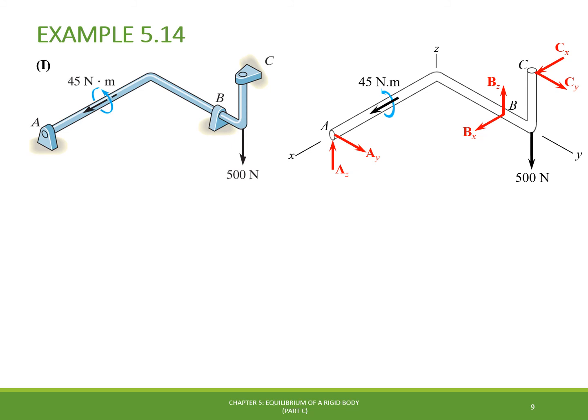And with that, the free body diagram is done, because the force reactions developed by the bearings are sufficient for the equilibrium, since they prevent the shaft from rotating about each of the coordinate axes. Because of this condition, no couple moments at each bearing are developed.